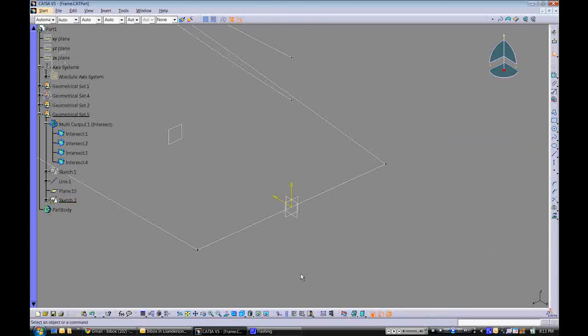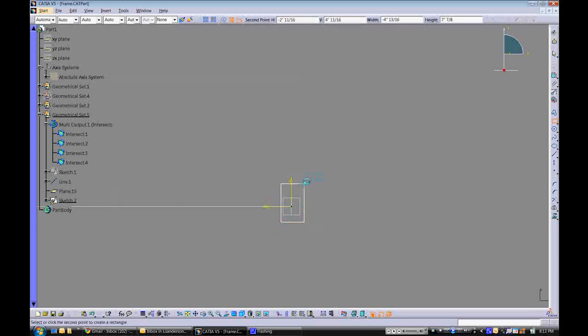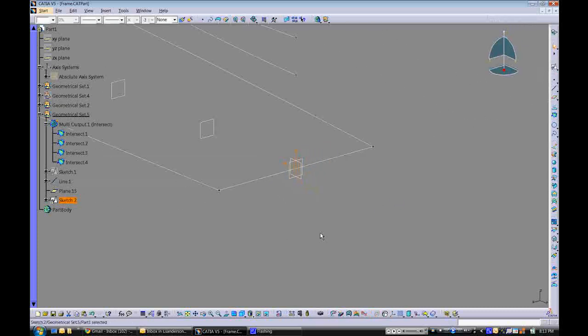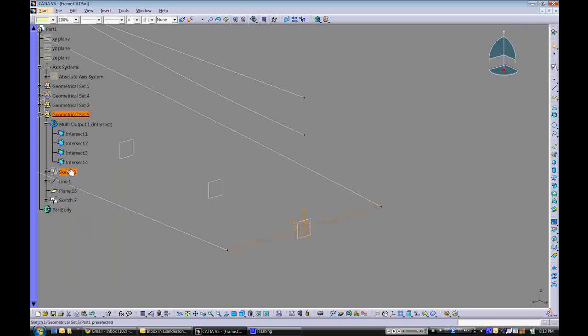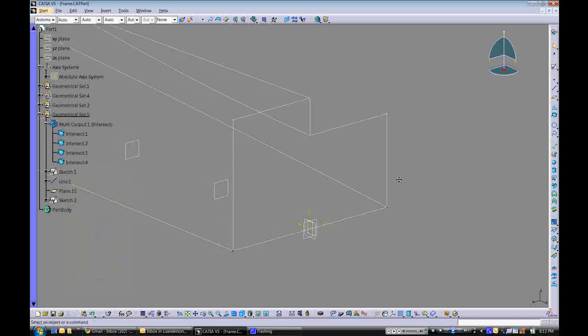So now we're inside of our sketch. We're going to use the normal view to switch to an orthogonal projection, and then we're going to draw a rectangular frame profile with the rectangle tool. And you can see that it automatically added horizontal and vertical constraints. So we can now exit out of our sketch, and we can turn our reference sketch back on. Oops. Hide, show. And now we're actually going to define a couple parameters that we'll use to drive globally the frame width